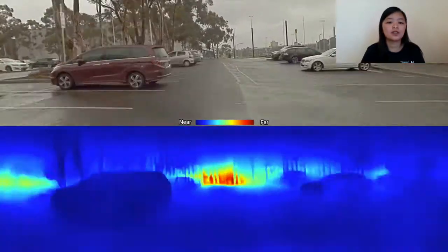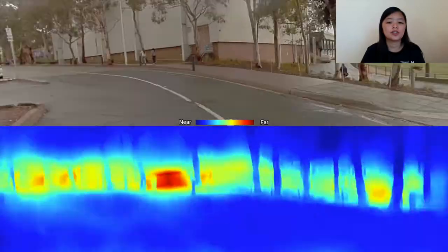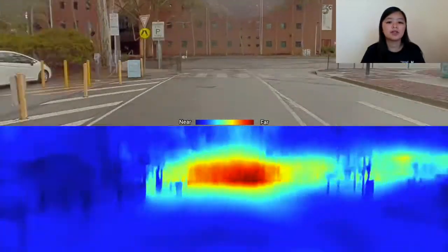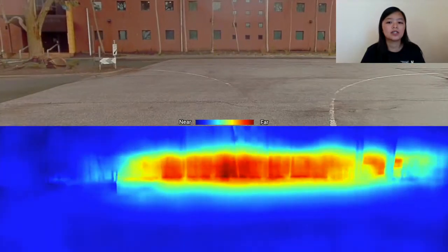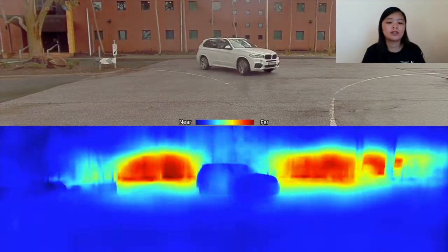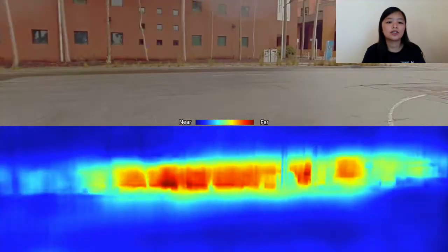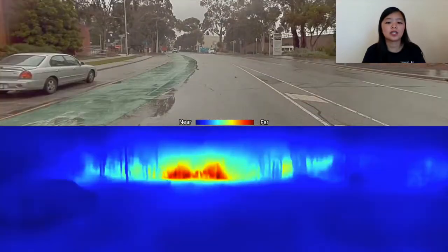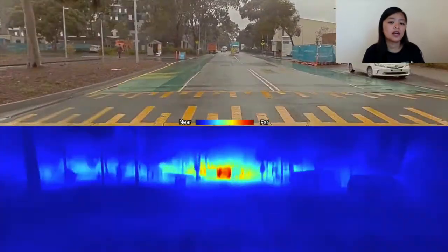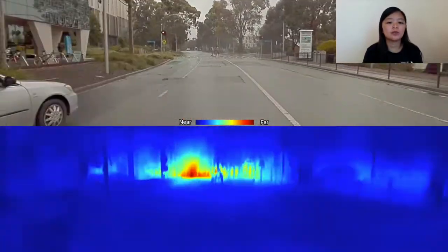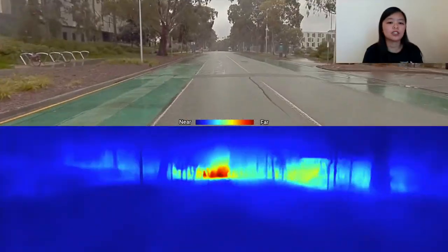The first used a neural network, written based on literature and trained on the KITTI dataset, a large outdoor dataset with RGB images and projected LiDAR data, which acted as ground truth. Transfer learning was then conducted with the team's recorded data. Due to inaccurate sensor calibration and data collection techniques at the time, there was misalignment between the ground truth data and camera images, and recording new data was not possible due to COVID-19 restrictions.